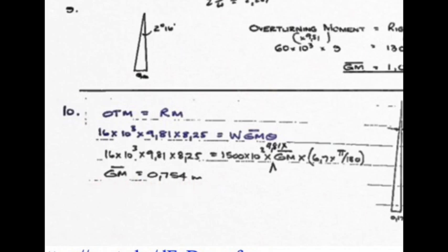So the practical use of this is, if the ship's captain did not know the metacentric height, he could use a pendulum or other device to measure the angle of roll, and he could move a known portion of cargo a known distance across the deck, and from the calculation find the metacentric height for his ship, which would indicate how it was loaded. Now, this rather alarming YouTube clip you might want to go and look at. It shows the danger of too small a metacentric height, or possibly an unstable metacenter position, resulting in a bit of a catastrophe. So have a look at that one.